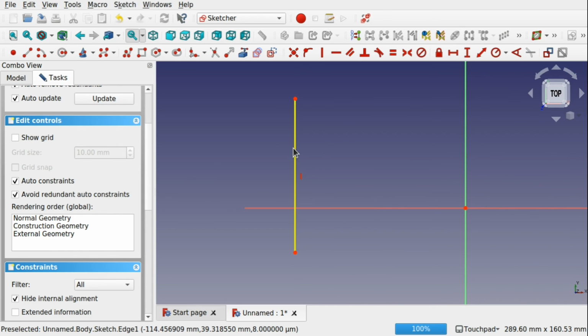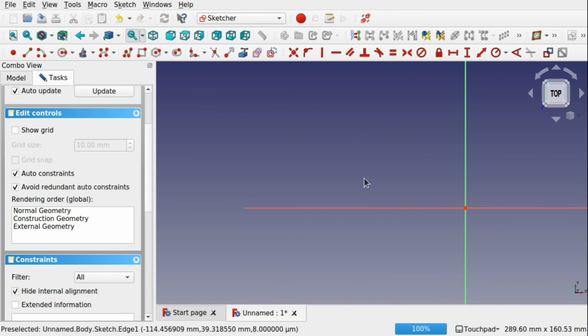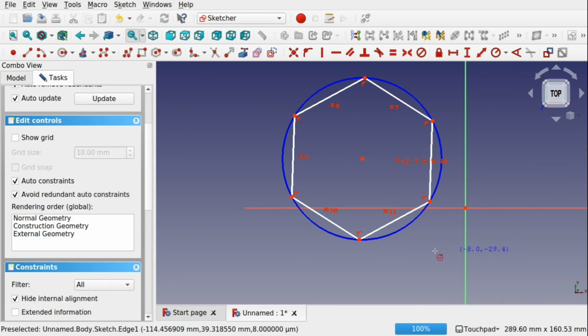The other thing is, at the end of the day, if you can work and not constrain, and you're happy in working in that environment, and you're not creating errors for yourself, it's not a 100% rule that you have to fully constrain something. It's best practices. It gets you out of problems. You don't have to do it. It's advisable to do it because a lot of problems will be fixed by you constraining properly and then having those constrained sketches. There's little shortcuts around.